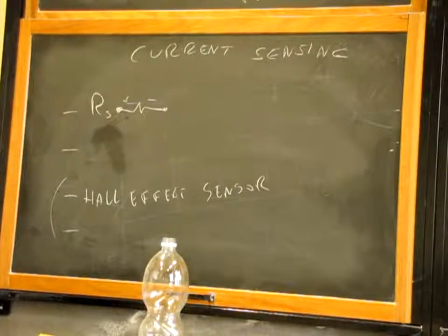And besides, an AC adapter works at high frequency, a few hundred kilohertz, and Hall effect sensors don't work well at high frequency. They're okay up to a few tens of kilohertz or less, and they are expensive. So for large power systems that are relatively low frequency and expensive, adding a $10 sensor is okay, but not in our class. This is the reason why it's in the third position.